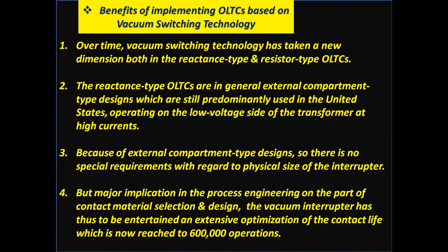The reactance type OLTCs are in general external compartment type designs, which are still predominantly used in the United States, operating on the low voltage side of the transformer at high currents. Because of external compartment type designs, there are no special requirements with regard to the physical size of the interrupter.